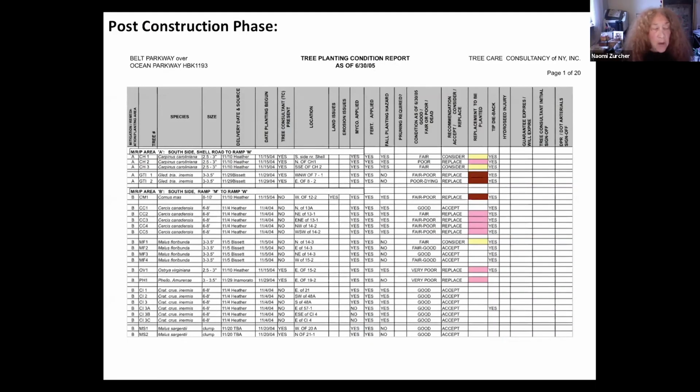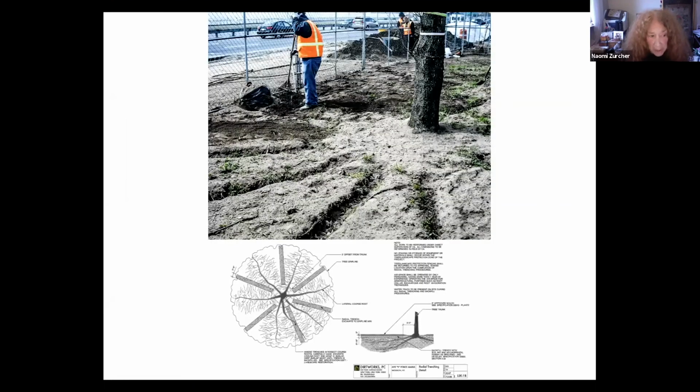Post-construction. Following completion of construction, the project consulting arborist must conduct an inspection based on the initial inventory to determine the extent of any impacts such as soil compaction within the TLPZ. Soil decompaction is best accomplished by specifying radial trenching with the use of pneumatic excavation, PE, such as an air spade.